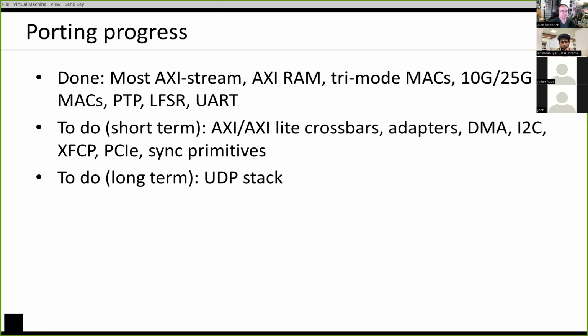So if you need a pulse sync, you just drop down the module, instead of what I was doing previously, which was ad hoc writing a pulse synchronizer when I needed one. There are a few modules I've updated already. Mainly I've been installing the reset synchronizer module in a bunch of other places. That'll make things a little easier to work with.